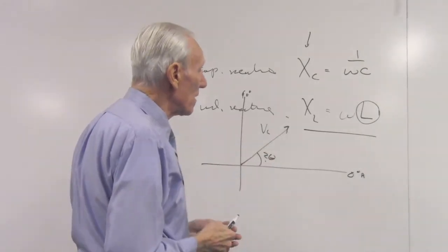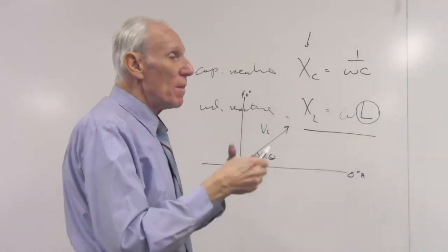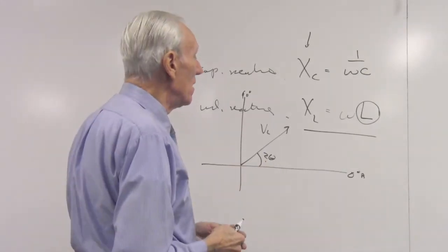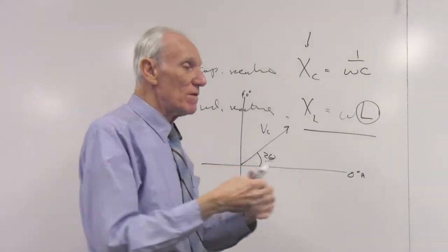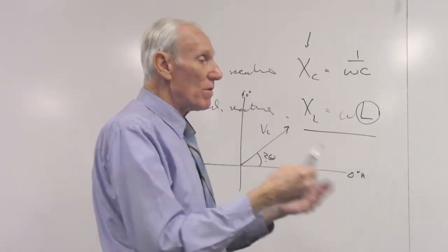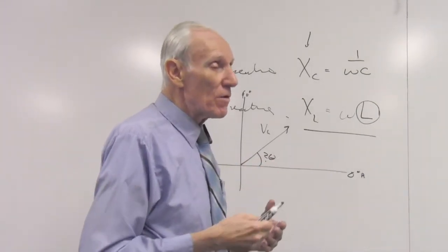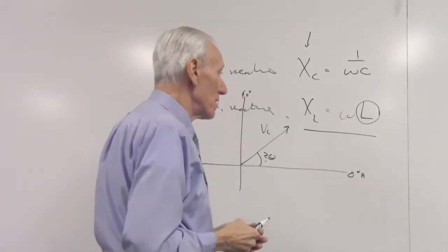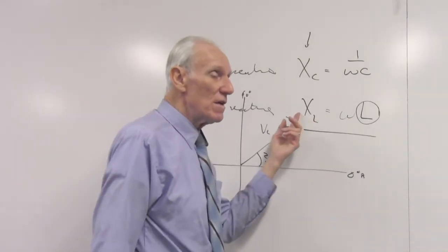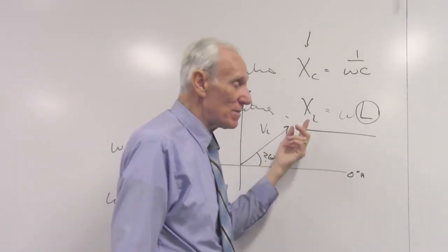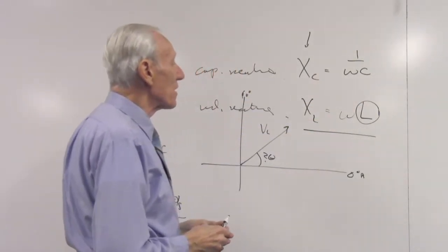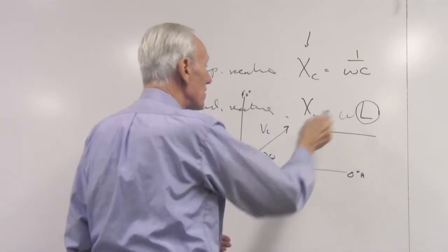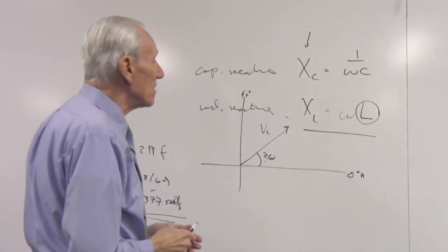And in terms of Faraday's law, it's the changing magnetic flux that gives you this term here. And if you have a circuit in which the voltage is changing faster, then of course the magnetic flux is also changing faster, and that increases the inductive reactance. So that's kind of the hand-waving explanation for why this is downstairs and why that's upstairs in these relationships.